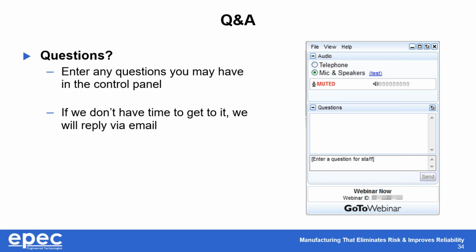Fourth question kind of goes back to the controlled impedance design question and why silver ink and shielding films are not recommended. As I touched upon before, one of the biggest challenges is achieving the correct dielectric thickness between the signal layer and the shield layer, which is now also required to act as a reference plane.